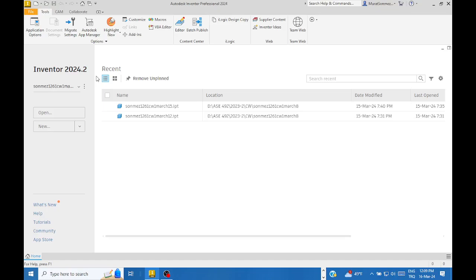And the other thing to know: when we use the calculation tools of Inventor, the stress analysis tool of Inventor, and then click on the Save button, the software, without notifying the user or taking the permission of the user, automatically creates a folder in the background, and the results of calculations are recorded in that folder.